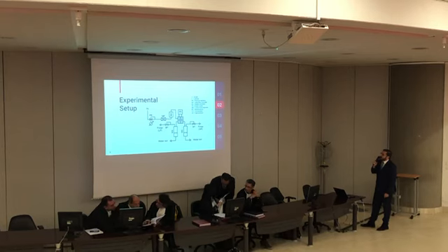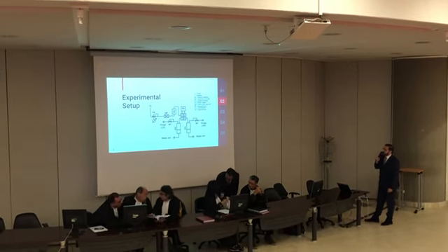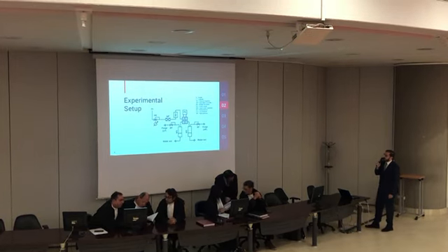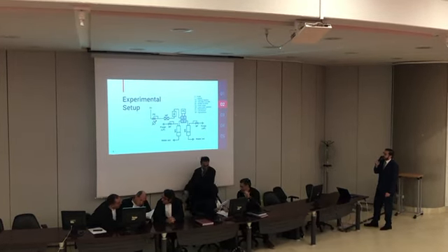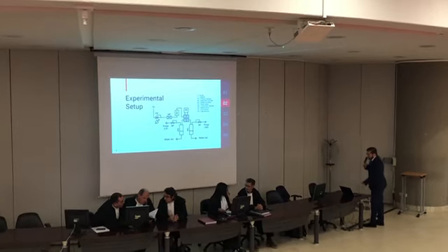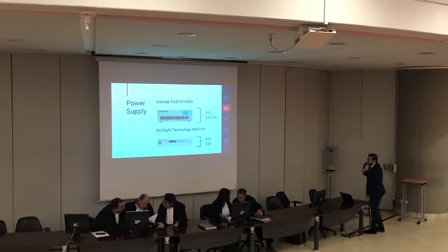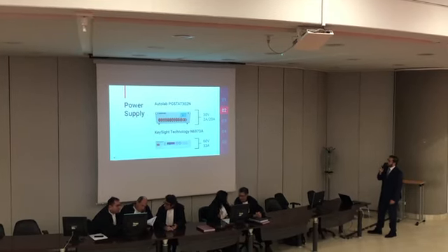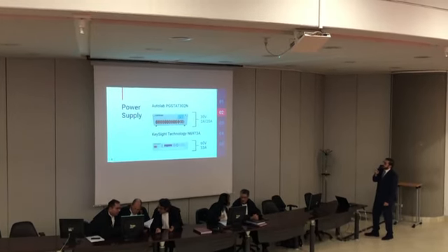Here is shown the experimental setup used for the measurements. In particular, the hydrogen is connected to the cell through a pressure regulator, a mass flow controller, and a bubble humidifier. Talking about the power supply, the devices used are 2: Autolab and Keysight Technologies.